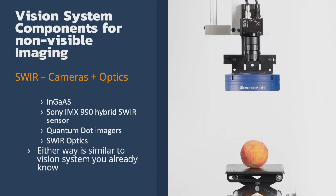Similarly, the other technology which has been helping us is quantum dot technologies like those offered by SWIR Vision Systems and others. Quantum dot sensors also lower the cost and work in a slightly different way. They are essentially a CMOS sensor and readout structure, but they have a colloidal quantum dot slurry put over the top of the sensor.